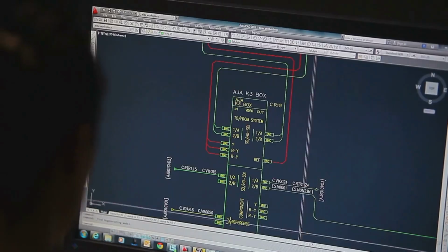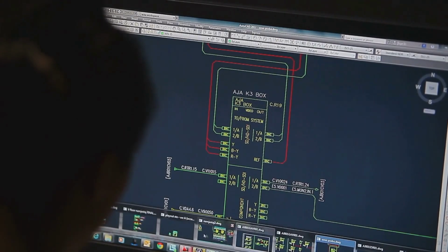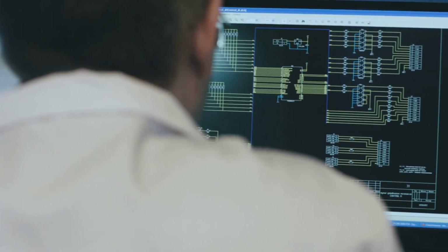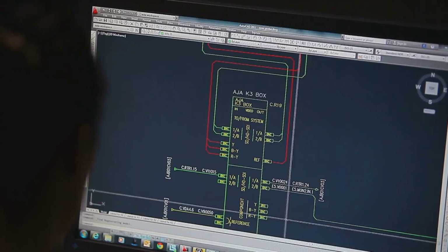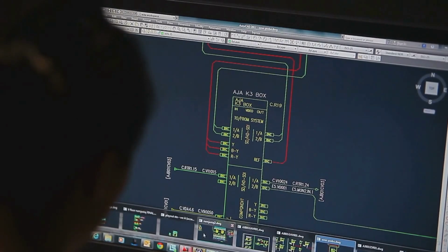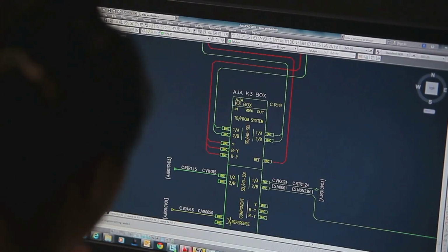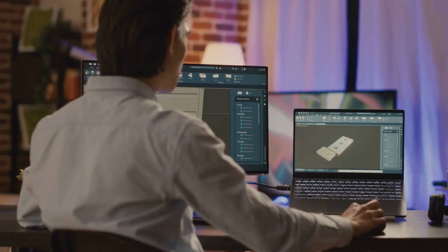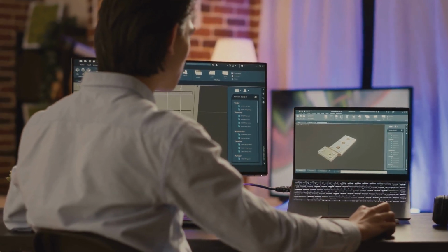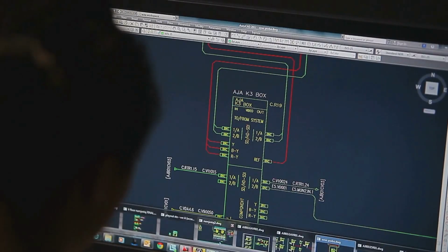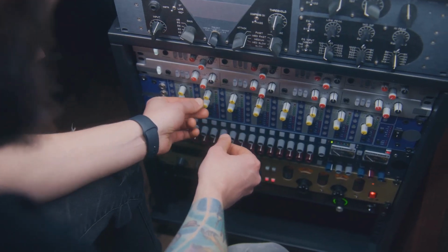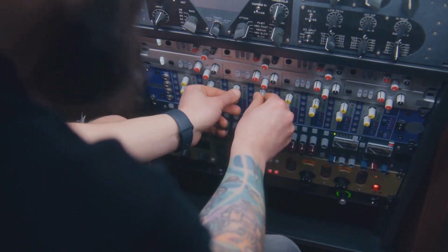First things first, we need to recreate our PCB inside CST Studio Suite. This involves importing our design files, typically in Gerber format. Think of it like uploading the blueprints of your circuit board. Once those are in, we need to define the materials. What's your PCB made of? FR4. What about the dielectric constant? These details matter, people. Accuracy is key if we want meaningful results.